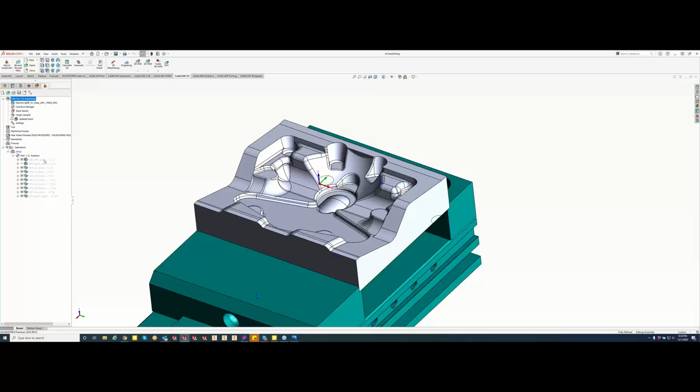Starting at the top, they were doing 2 different HSR operations right here, but we had to tell it what areas to keep it contained to. We had to tell it what feed rates, different areas, what the scallop or the step down was going to be for those specific areas, where now, this is my favorite part. Open up our 3D iMachining here.